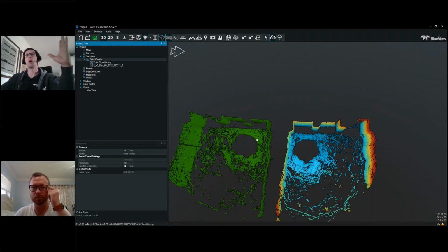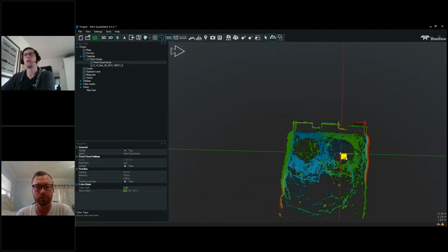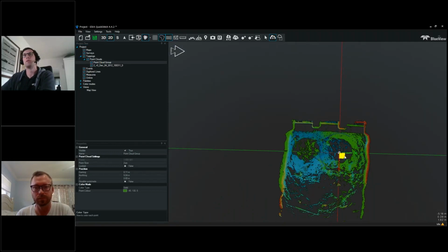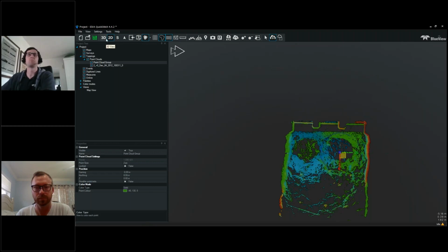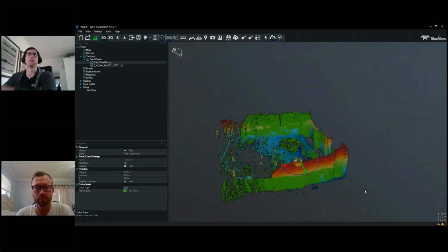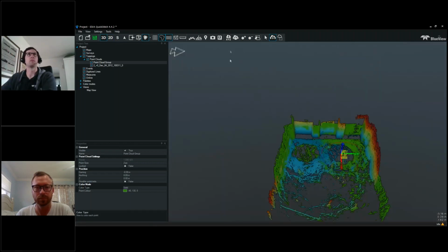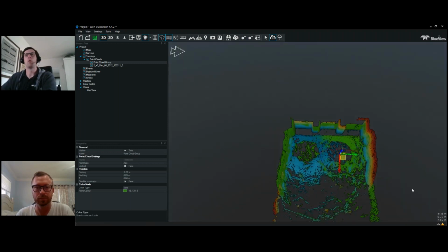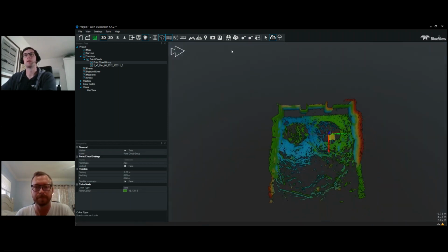So I want to align these properly, and a lot of people would say, okay, you can simply just use that transform tool and just do it kind of by eye. Like I can use the 2D tool, I can align these back walls, maybe rotate it a bit to line it up. Okay, and those look pretty aligned, but generally that's not going to be a high accuracy alignment. That's going to be a quick and dirty alignment. So if you really want more survey grade results, that's where the software tools come in, using the software tools to really get a tight registration.